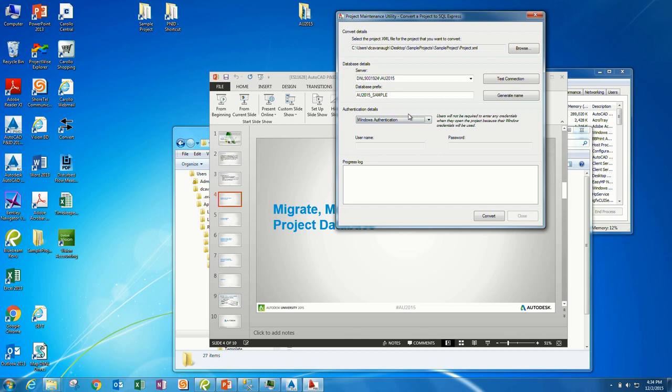And there is a white paper about using or implementing SQL with Plant 3D and P&ID. It takes you through SQL Server Management Studio and how to set up different permissions based on the network environment that you're running in. So that's a very helpful document.